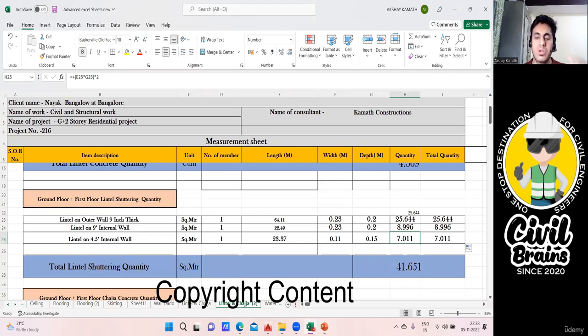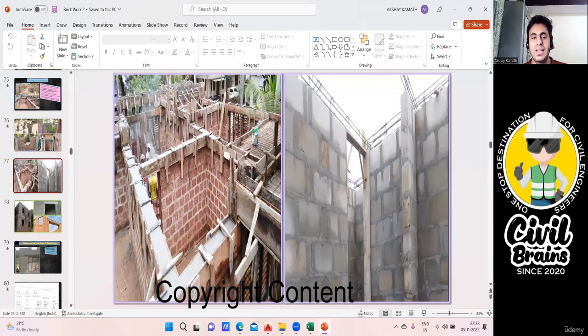Now you may have one doubt. Everything is fine, but in the lintel portion near the door, we are not putting the bottom. Always remember, I'll tell you two things. If it is a normal house construction, wherever the brickwork has happened, over that only you have to do the lintel. In that case, you don't require the bottom, because this brickwork itself will serve as a bottom.